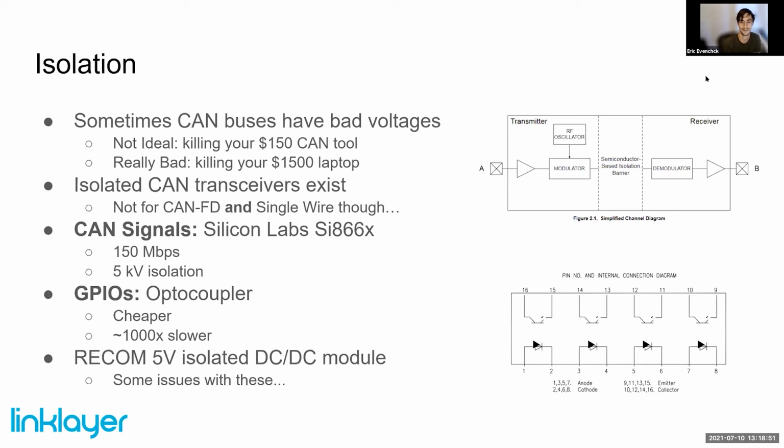So I had a handful of devices that came in and failed or did not work or passed testing. And with one of them, it was because the DB9 connectors on it were, somehow they used male pins, but a female shell. And I don't know how that happened, but that DB9 connector was toast. And all the other failures, which was just a handful, maybe 1% or less than 1%, was the DC-DC module that had failed. And those just shorted across and got real hot when you plugged them in. So unfortunately, this nice device does the trick, but seems to have a failure rate higher than I would like.